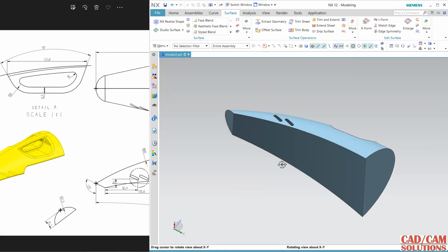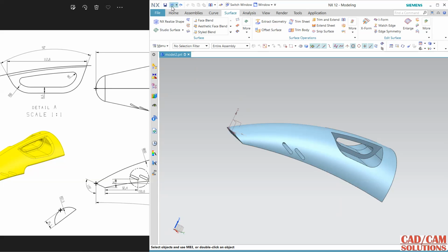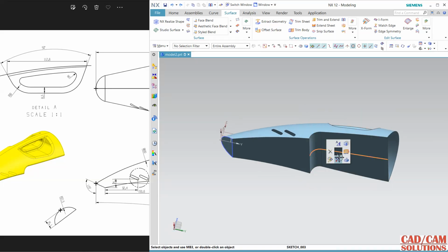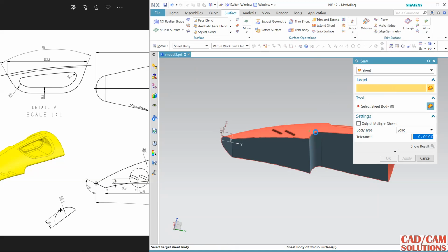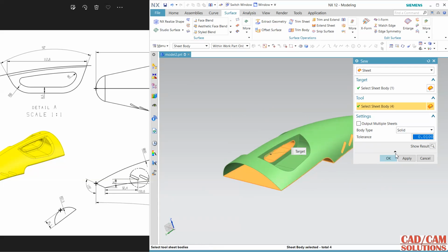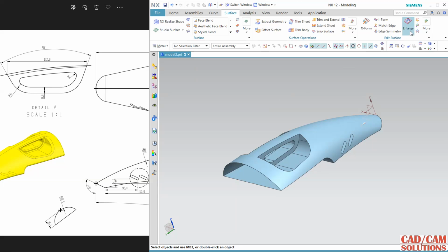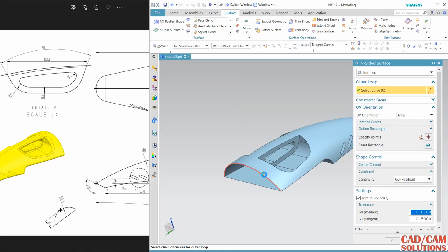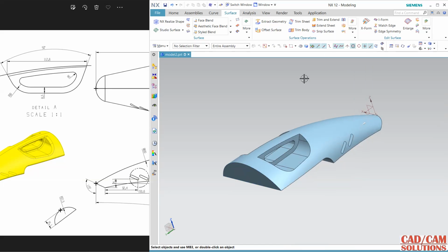What happened, it is white, come, undo, undo, undo, now use sew this surface and rest of the surfaces, wait, this is missing, go to this, and inside the surface, fill surface boundaries, anything you want, just select, okay, now sew.